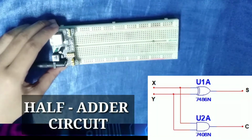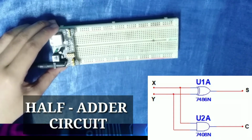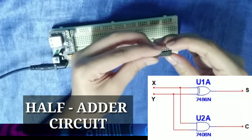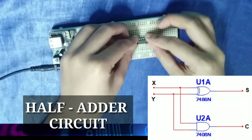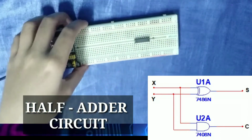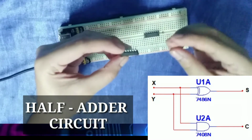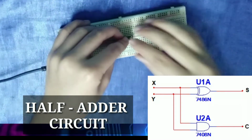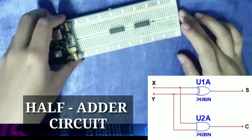Now, for our first logic diagram, which is the half adder and full adder, we will be needing a 7486 XOR gate. Okay, so let's connect it here. And we will also be needing a quadruple input AND gate, which is the 7408 AND gate. So let's just connect the components on our breadboard.